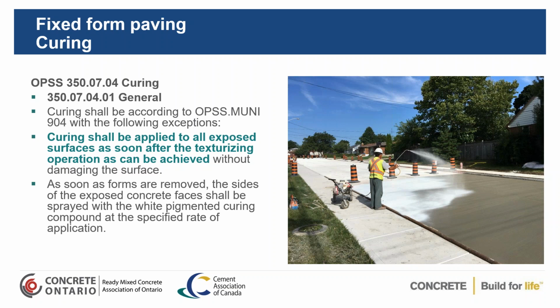He's covering that up now so that the concrete is going to retain that water in it. It's going to get complete hydration of the cement, so you're going to get the strength gain that you want, and you're going to have a very good, strong, durable surface as well. The curing shall be applied to all exposed surfaces as soon as you're finished texturing.